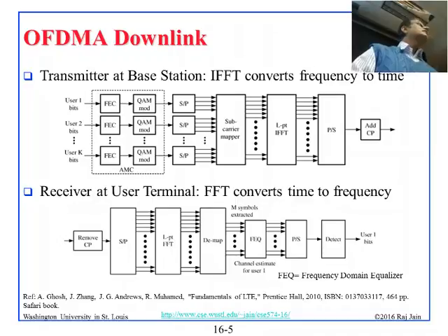It is just like interleaving, in some sense, yes. Interleaving is generally used for bits in the time domain. This is frequency domain interleaving. In the time domain, you take the bits from this and this guy and then mix them together. That is interleaving, right? So this is frequency domain. These are all frequencies, and these are all frequencies coming out.